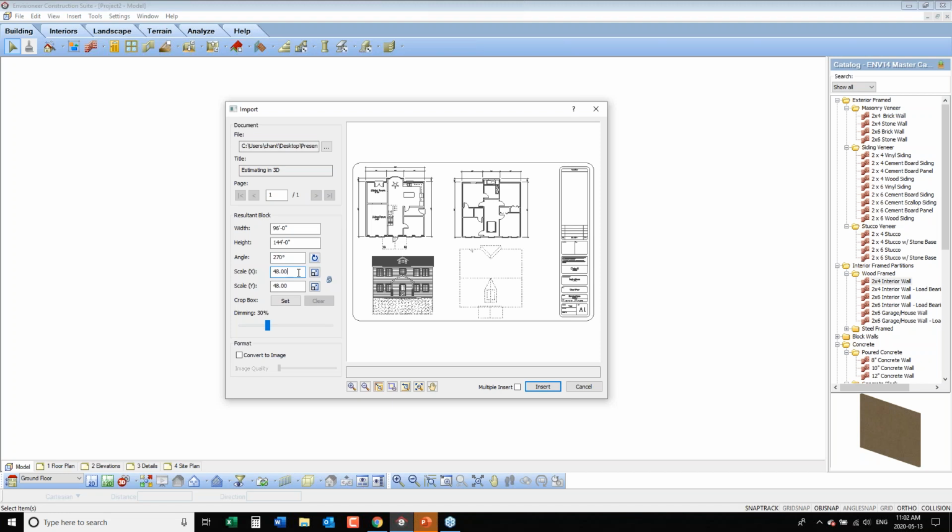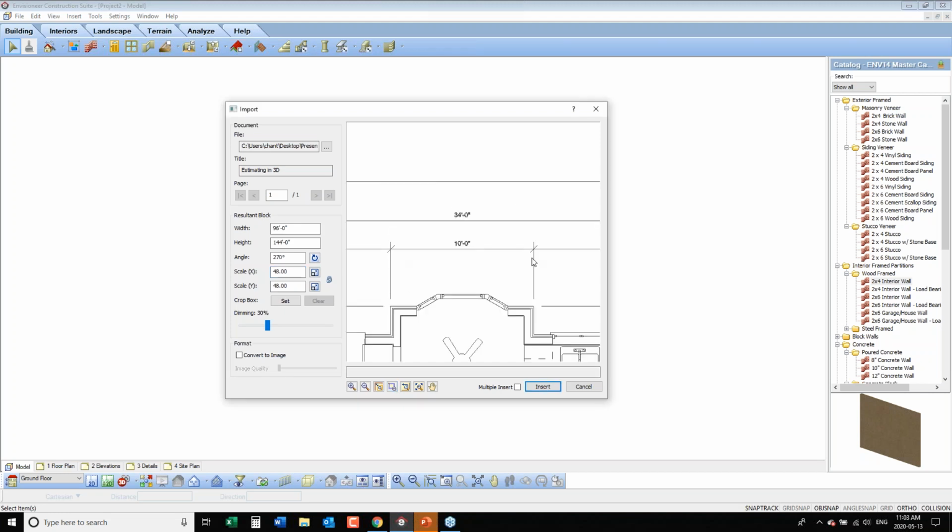Another important aspect when you're bringing in an initial PDF, what's the scale? We can never really trust that PDF that you're bringing in. They might have written down the wrong scale. So I'm going to zoom in on a known dimension here that they've put down, this 10-foot dimension. I can calibrate that PDF and scale it correctly using this button right here called Pick the Scale.